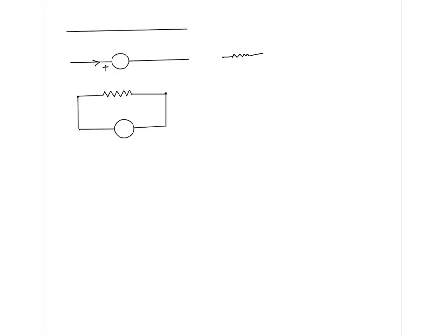The moment the voltmeter is connected, some current that was all going through the resistor earlier must now go partly through the voltmeter. If 5 was coming here, 5 was going there. Now, if the voltmeter takes 0.5, then 4.5 will go here.